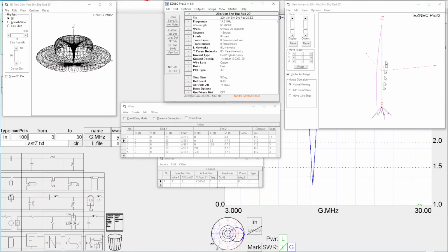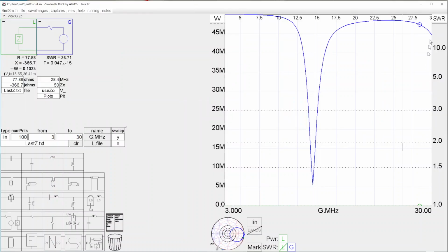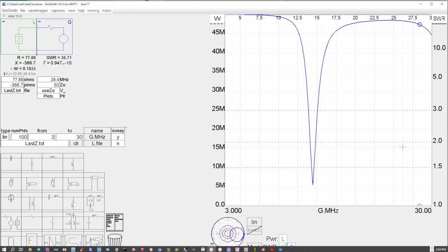Okay, I can see a lot of current on the vertical. Then I can have these distributed currents that add up, though, because each one of these currents have to totally add up on the 4 radials to the single current in the other direction, going up onto the vertical portion. And so now let's see here. I've got one nice curve, and oh look, it's probably another dip out here above 30 megahertz.